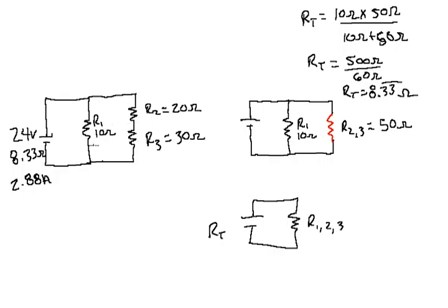So we can write that in, 24 volts here. Now this whole branch has 24 volts. So this resistor does not have 24 volts, and that resistor does not have 24 volts, but combined going across it has 24 volts. So we're better off writing it over here.